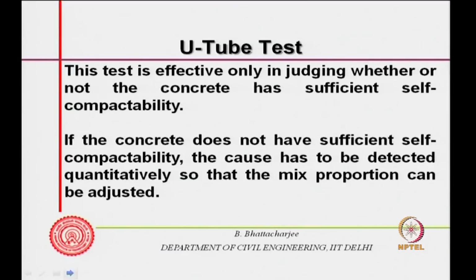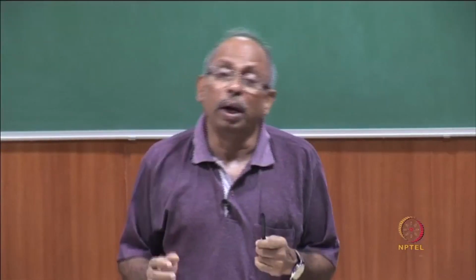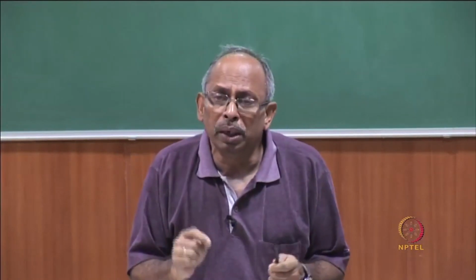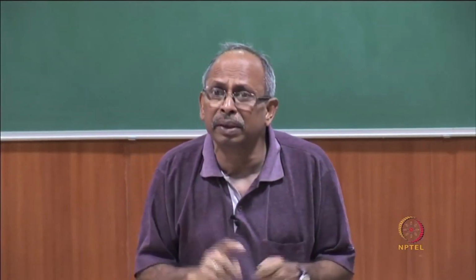This test is effective only in judging whether or not the concrete has sufficient compactability. Will it compact itself? It will not be able to judge the flowability to a great extent, or other requirements like segregation resistance.